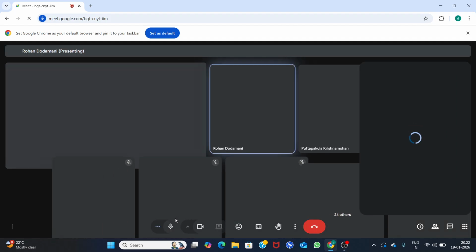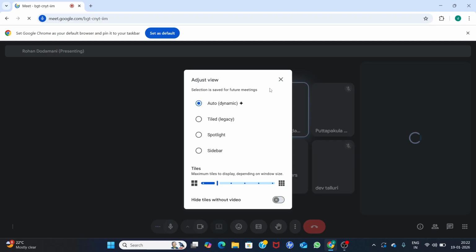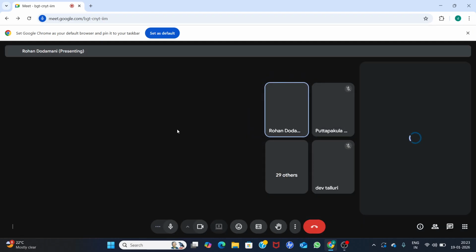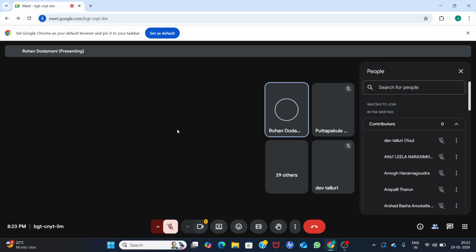It will require continuity for the cells, so from one block to another block it will start the continuity. For that purpose we need to add the filler cells and fill the empty spaces with filler cells, also for density errors. That is the main thing.